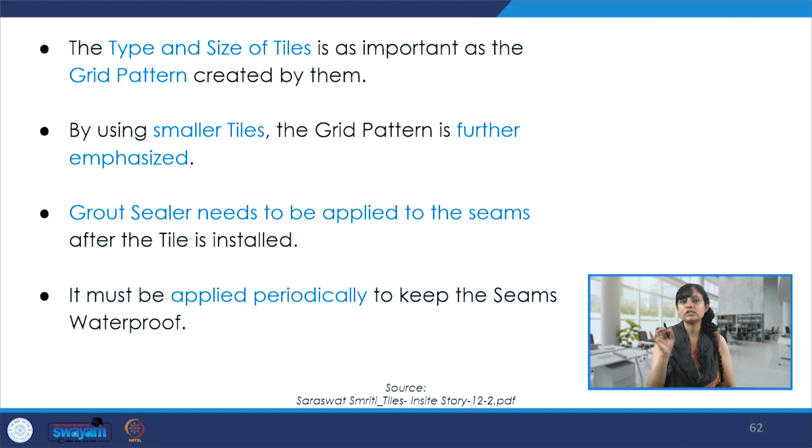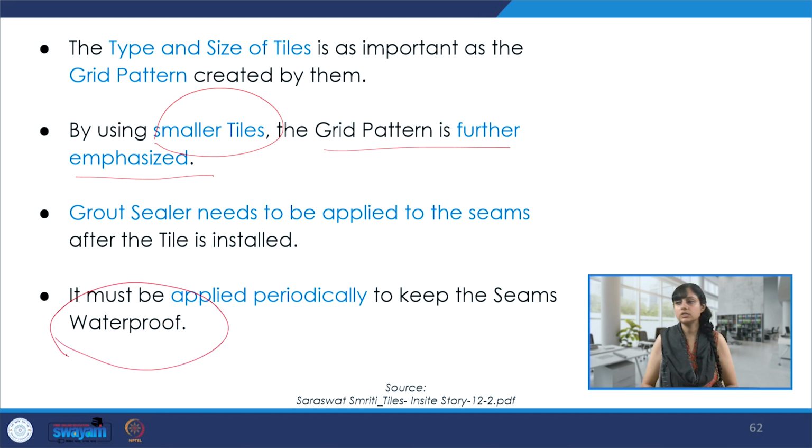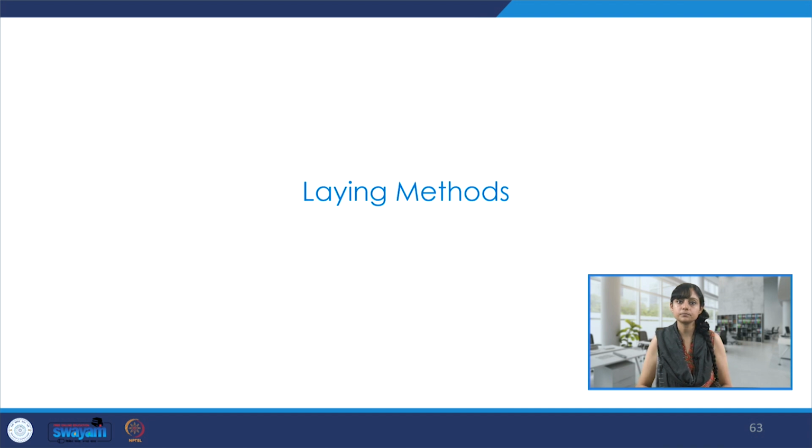The type and size of tiles is as important as the grid pattern, which is created by putting them together. So by using smaller tiles, the grid pattern is further emphasized. So it could be a choice of the designer to use smaller tiles and have an emphasized pattern. The grout sealer needs to be applied to the seams after the tile is installed. It must be applied periodically to keep the seams waterproof. So these are all important points.